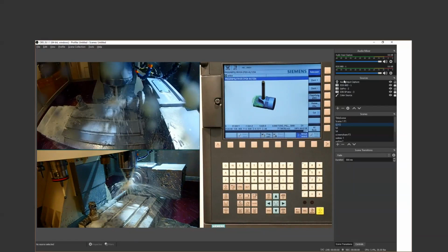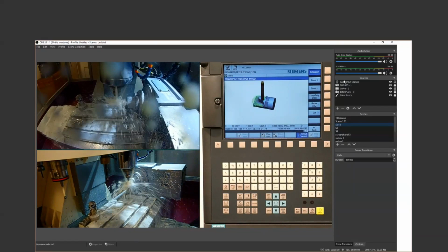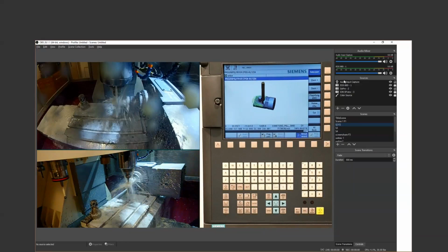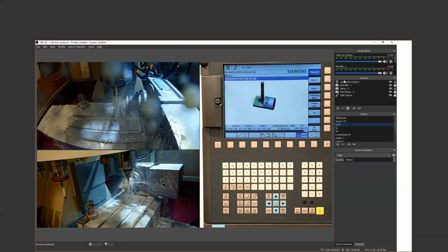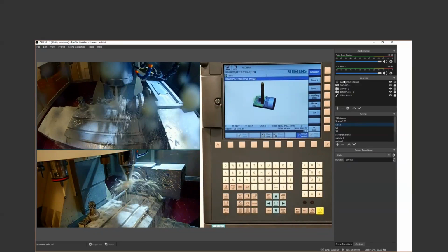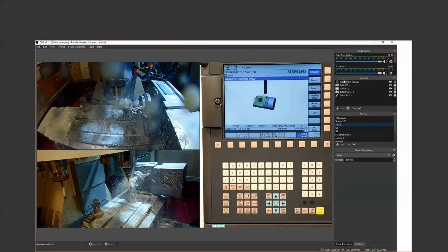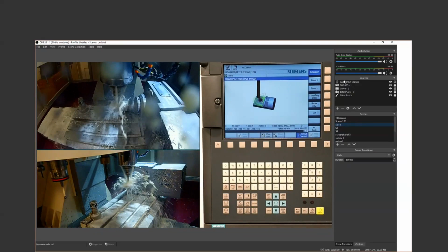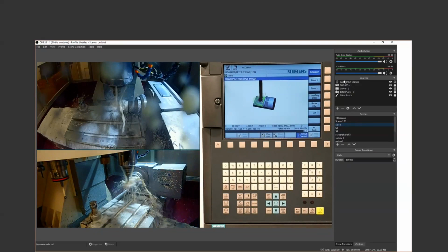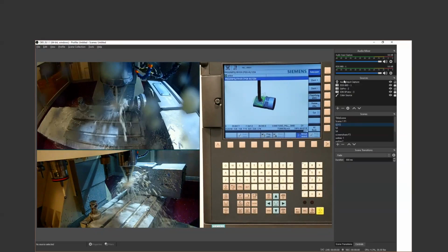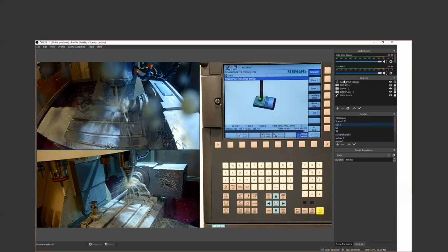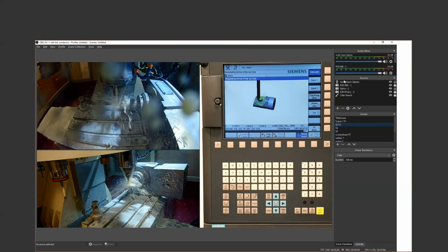Of course, you notice when Mike programmed it, he didn't say anything about cycle 832. So, Mike, how did it know to leverage our advanced cycles that we have in the SINUMERIK control while you were programming in NX? That's all based on the type of method I chose and the post processor. So basically, it's happening automatically, right? Correct. And just another reason where you bring all this stuff under one roof, and it makes things a lot easier to optimize the whole process chain.